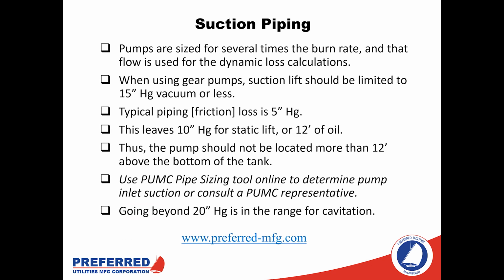Taking a look at the piping now, we have the amount of fuel in our system and we have how fast it's moving. And now that we have that general flow rate, we can start sizing things like piping and valves. Now, when we take a look at our system, if we remember the overview we looked at earlier, all of the piping that's in the system, even though the piping between the main tank and the transfer pump set may be the shortest run of piping physically in the system, it is going to be 90% of the consideration for designing and troubleshooting in the field.